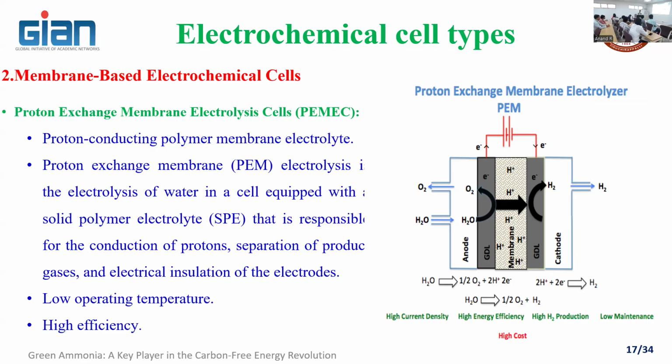It's something like a sandwich, so this and this can be sandwiched in between this. Even the pressure applied over this plays a major role. Normally, if you operate at ambient temperature, it will not create any issue. But the Nafion membrane, you are going to coat one side with the catalyst support for the anode, and the other side with the catalyst for the cathode. So the catalyst coating also plays a major role. When you apply a coating of certain micron or nano thickness, we need to ensure that the catalyst is coated as a thin film. So the life depends on the catalyst material, and also on the operating temperature and pressure.